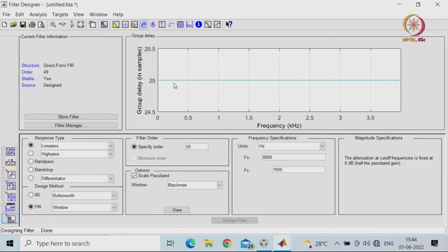That delay, because I will be combining it, if you remember your structure, comes down by half basically. So, the constant delay of this filter is going to be 25 units. After that you will be getting your output continuously if you are running for your real time applications.